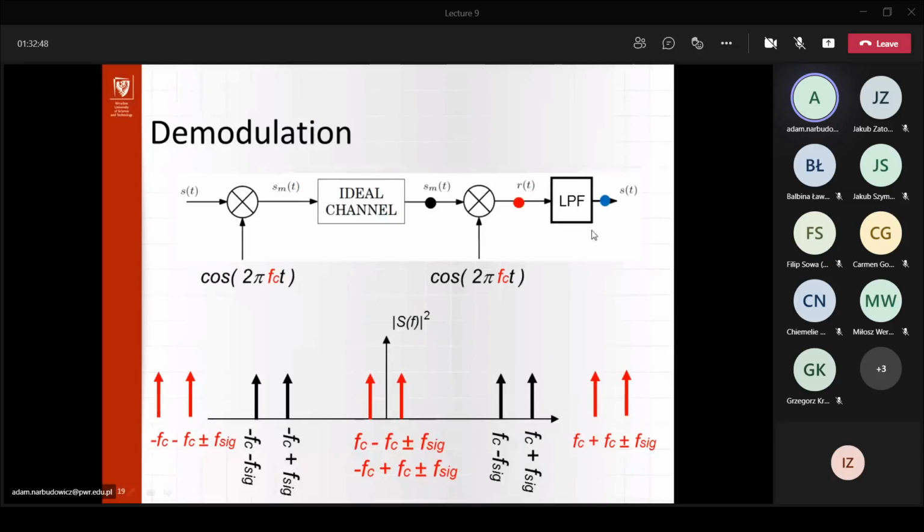So at the end of the day, we would use a low pass filter simply to extract only the low frequency components, and the rest just unfortunately goes to the bin. We filter out this very fast changing component, and with this you can recover the slowly changing F signal, and then you can do further processing at low frequencies by applying the diode and extracting the envelope of your signal from the slow frequency components.